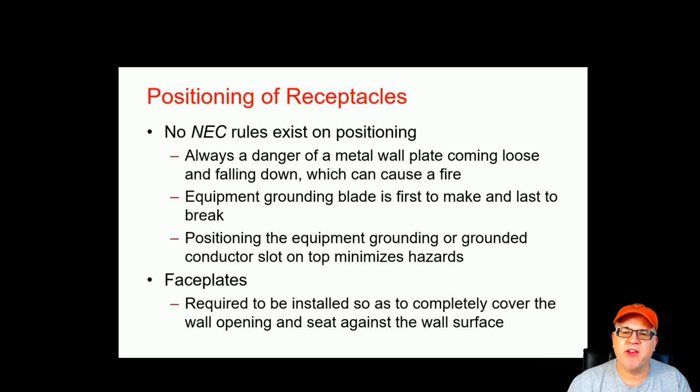Okay, now the position of the equipment grounding conductor or grounding conductor slot on top does minimize the issue for metal plates, but there is no requirement. Now, you might have a local code that requires that in those multifamily dwellings or commercial buildings, but it really can be any way you want it. Some people in a bedroom, for example, if they switch a receptacle, they might turn that one receptacle with the ground up and all the other ones with it down so that at a glance, you know which receptacle is the one that's being switched. Again, that's something that you would learn over time and maybe you incorporate into your layout, but it's not a requirement anywhere.